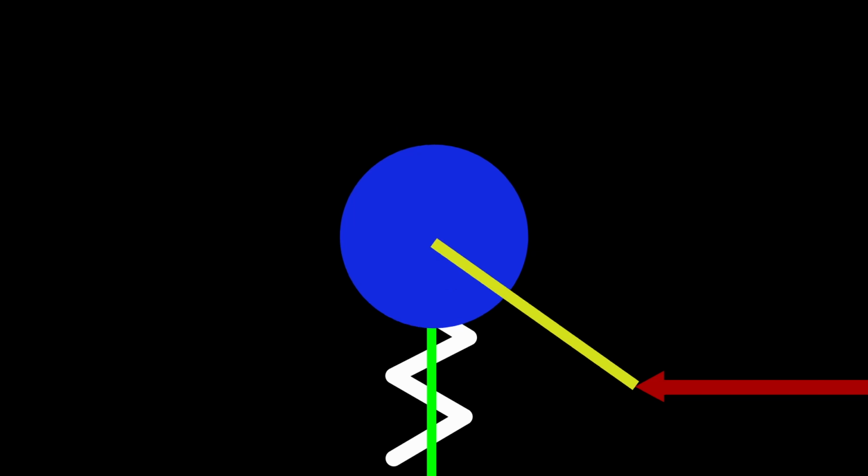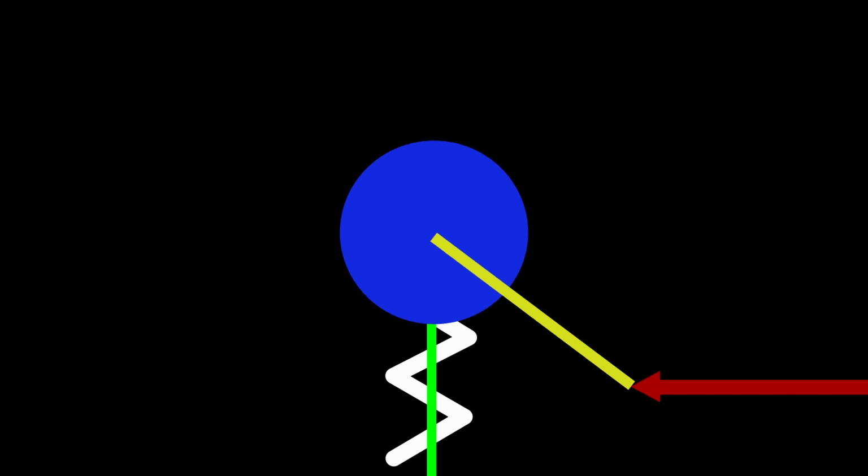The force on the tire can be higher than the actual total mass of the chassis. So that's going to be an increase in normal load, which means increase in lateral force while the chassis is accelerating upwards. And again, once it stops accelerating, the total force on the tires is going to just sum up to the total force of the chassis.